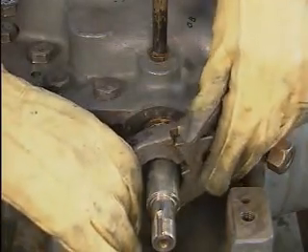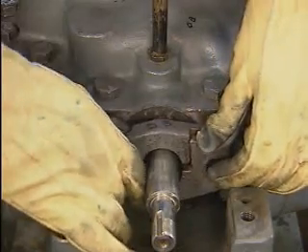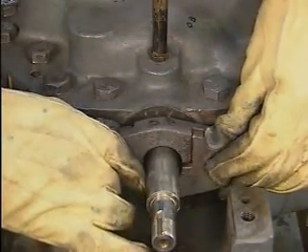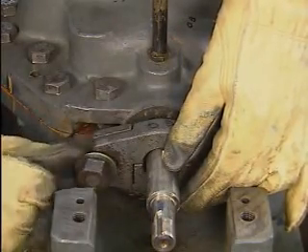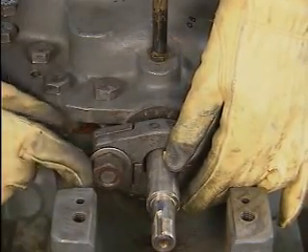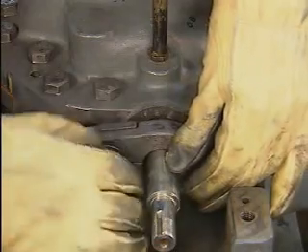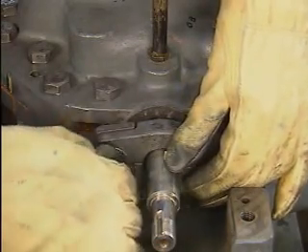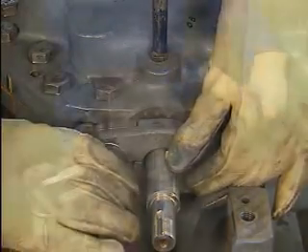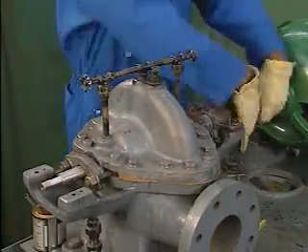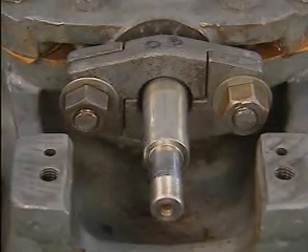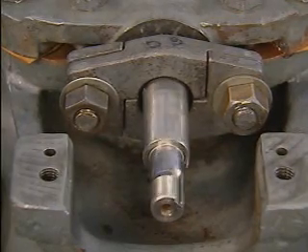After all the rings of packing have been installed, the mechanic reinstalls the gland follower. He positions the gland follower over the last ring of packing and then reinstalls the nuts that hold it in place. He tightens the nuts just enough to allow the packing to seat firmly inside the stuffing box. Next, the mechanic rotates the pump shaft a few turns by hand. If the shaft is difficult to turn, the nuts on the gland follower can be loosened slightly.